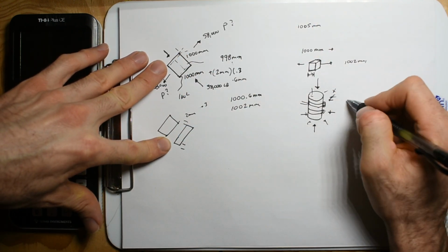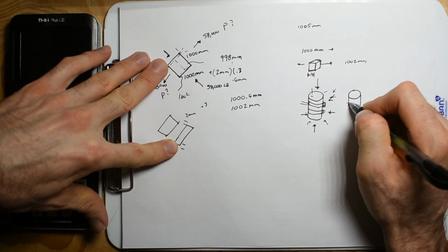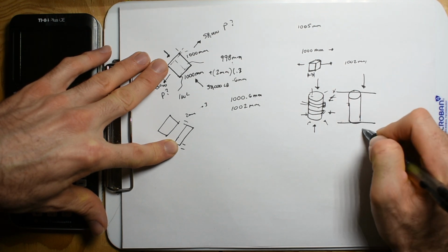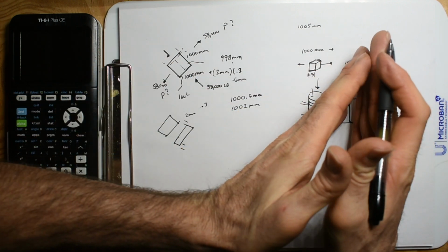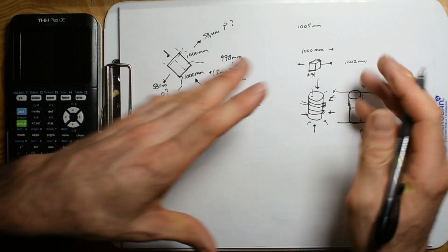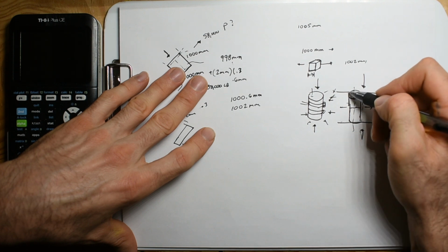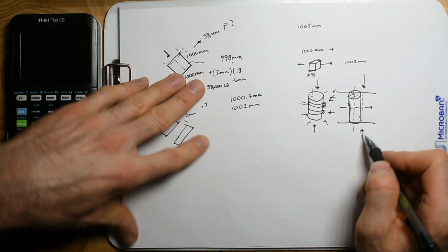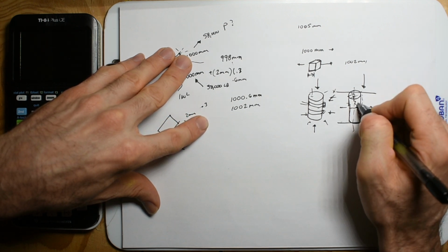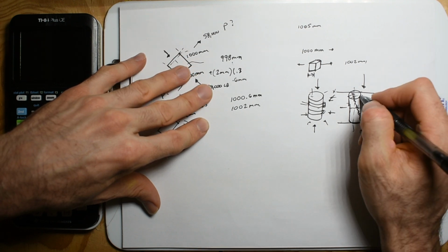I kind of wanted to do this with chalk. It never really worked. And maybe I'm missing a fundamental. But I threw one of these pieces of chalk in a vise and then squished it. And then I thought that Poisson's ratio would change its length this way, but chalk not wanting to move in tension, being pulled outward, that it would split in half some way. It never really did that. But it did cleave at 45, or steep angles. So maybe that's close to what would be going on there.